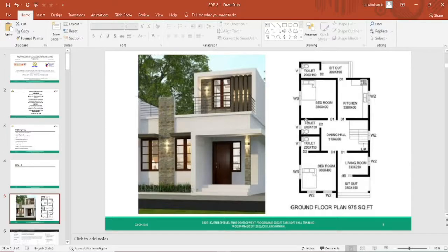Everything will be covered in this, and the live load has a separate code book. IS 875, we have a separate code for that. Part 1 specifies the dead load for each and every material. Part 2 gives the live load. So for a residential building, let us have a live load of 3 kilonewton per meter square.